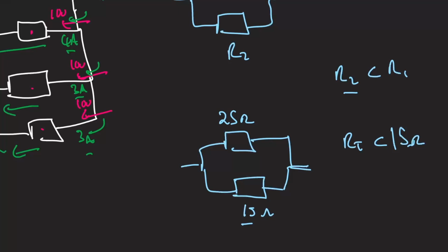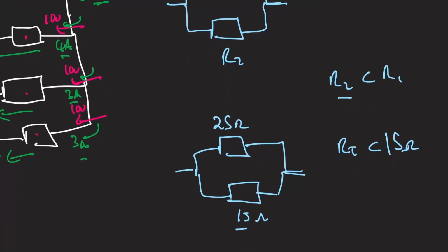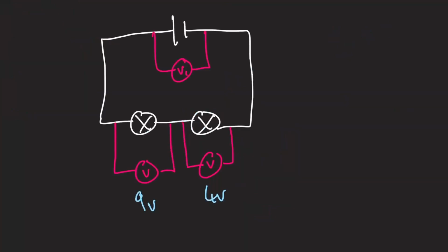When you have resistors connected up in parallel, the total resistance is actually less than the smallest resistor in that parallel connection. And the way we explain this is basically that you're giving the current more options to flow, or more branches to flow through, so the resistance is actually decreased, right? So because the current has the option to flow through here, or the option to flow through here, it's got multiple options, you could even add more branches over here if you wanted to, and because you're giving the current all these options, then the total resistance is actually less than any individual one resistor, okay?